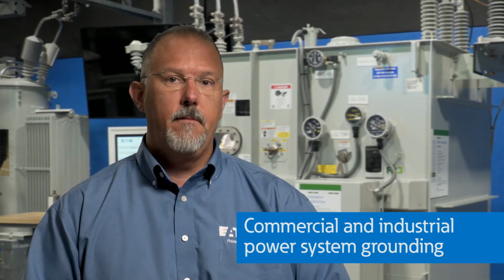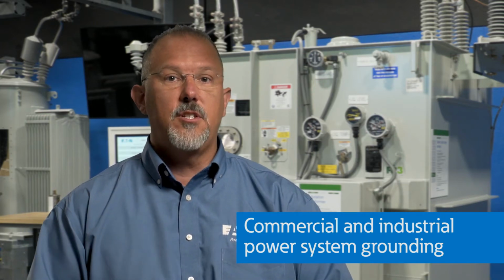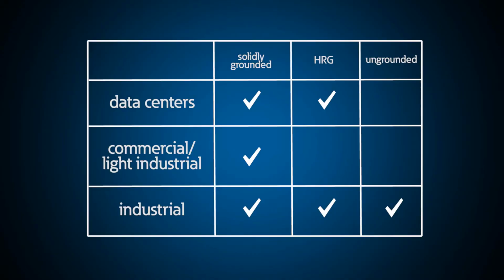So now let's look at a commercial power distribution system. As you get outside the residential world, you have more options based upon the applications. For example, data centers and other systems that demand a higher service continuity may opt to use high resistance grounded systems as opposed to solidly grounded systems. Many commercial and light industrial systems will be solidly grounded.